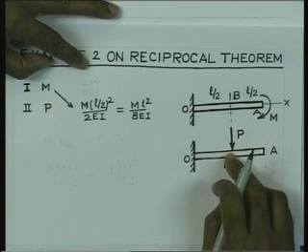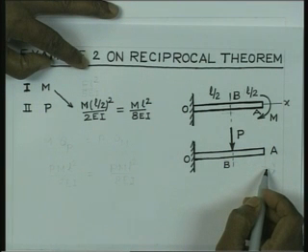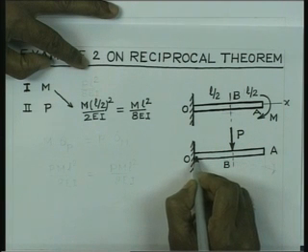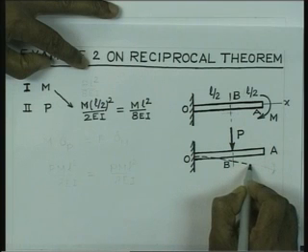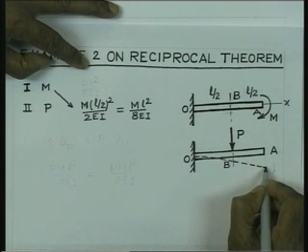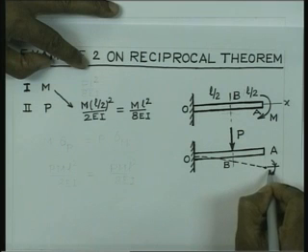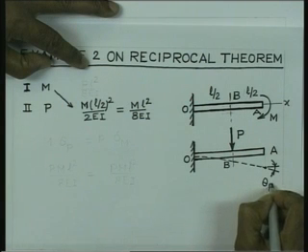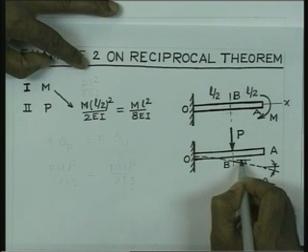When P is the force acting here, that force is going to produce a rotation at this point or deflection at that point in the same sense as this bending moment. Look at this case, here the deflection curve is going to look like this, it is going to deflect and then it will remain like a rigid element from here to this point, and therefore, the slope here is going to be this one. So, that is produced by P. So, therefore, let us indicate by theta P. In fact, that theta P is same as the theta at this point.